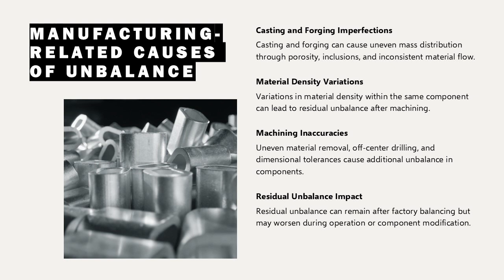Although many rotors are balanced at the factory, residual unbalance may still remain within acceptable limits. However, when operating conditions change or components are modified, this residual unbalance can become significant. Understanding manufacturing-related causes helps engineers distinguish between inherent design limitations and faults introduced later during operation or maintenance.